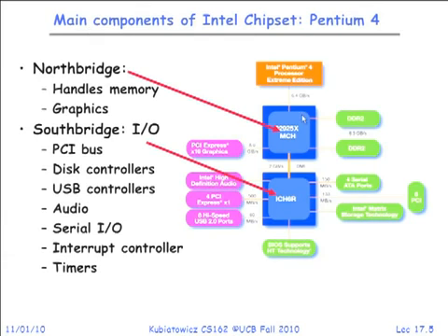Why do I say that this set of things here is slow, whereas this set of things is fast? What's slow versus fast here, do you think? Yeah, if you look at the diagram of the bus, the north bridge is multiple gigabits per second, whereas the south bridge is slower. Look at this, 150 megabits, 133 megabits. These guys are gigabits per second, gigabytes per second in some cases.